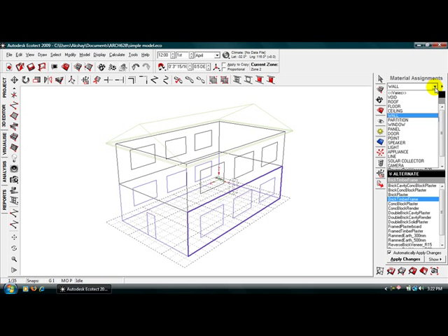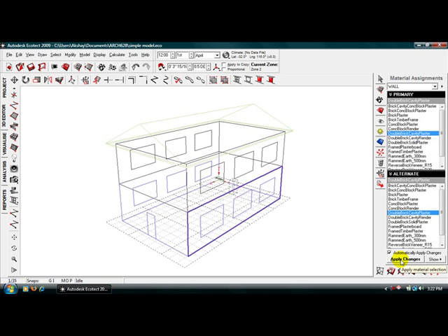Here you can see the various types of elements. You can also choose any one of these elements to change. Right now, since it is a vertical surface, you can have it as a wall, a partition wall, or just a panel. But let's say we want to keep it as a wall. Then you can choose any one of these types of walls. Let's say for example we want a double brick cavity plaster. So we select it and then we just hit the apply changes button.